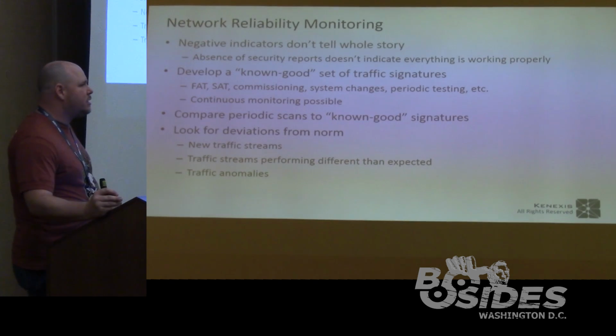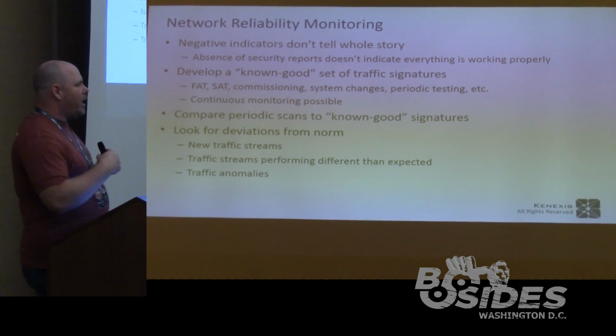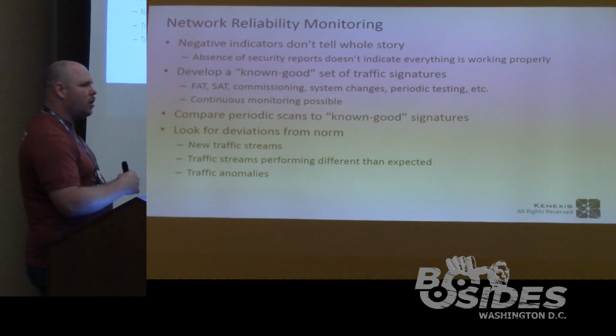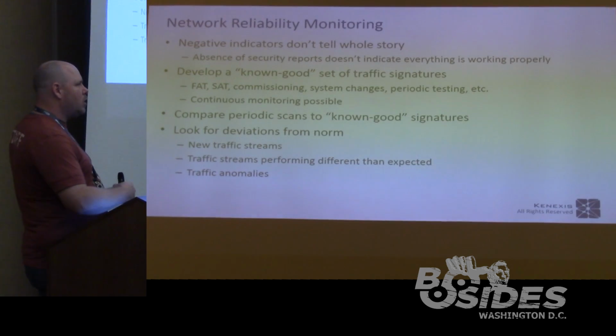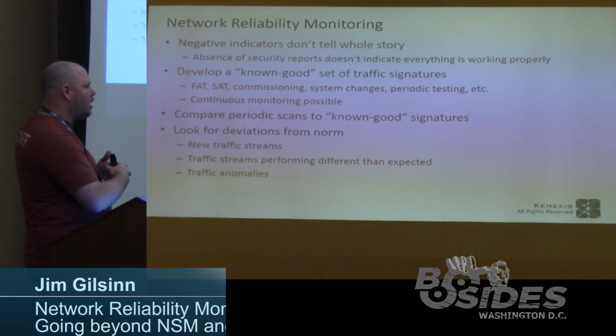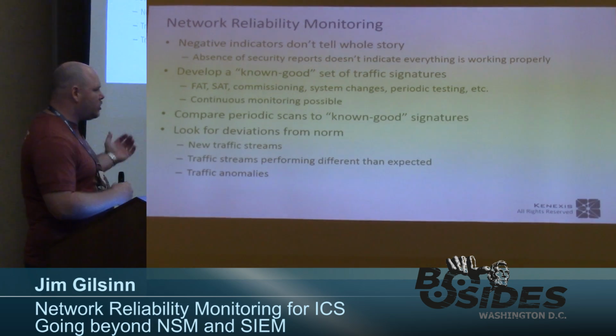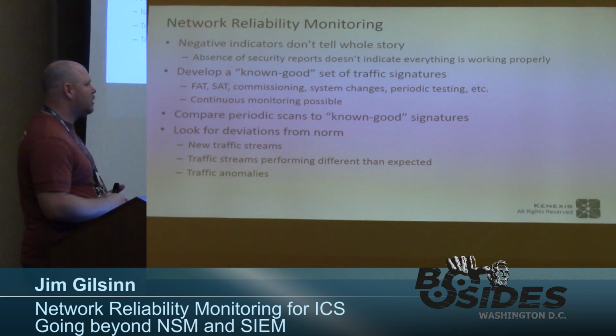Developing a known good set of traffic. I have not walked into a plant yet where anyone knew what their traffic looked like on the network. They knew what it should kind of look like, but they had never done full traffic captures and gotten to the point of isolating each one of the traffic streams and seeing what it should look like.